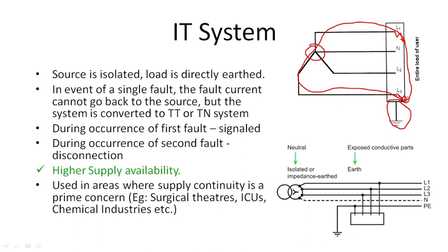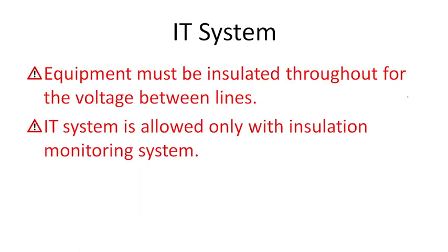Therefore, dedicated, additional fault detection schemes we have to employ if you are using an IT system. Normally we use the IT system in places where continuity of supply is a prime concern, like surgical theaters, ICUs and chemical industries etc.